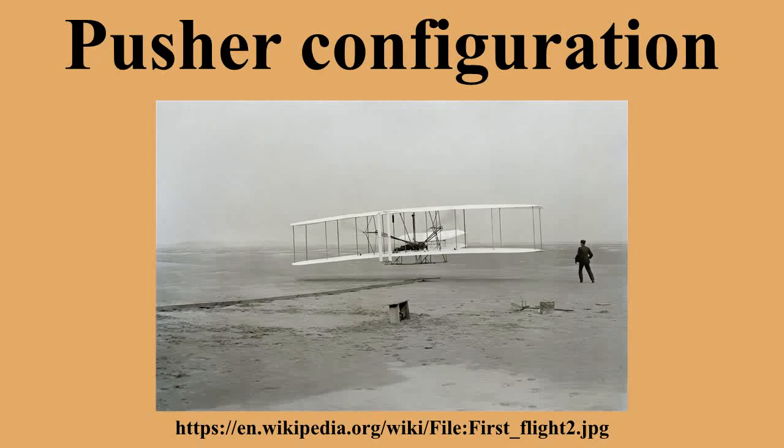Power plant cooling design is more complex than for the tractor configuration, where the propeller forces air through the system. Configurations. Aerostatic airships are the oldest type of pusher aircraft, going back to Frenchman Henri Giffard's pioneering airship of 1852. Aerodyne pusher aircraft have been built in many different configurations. In the vast majority of fixed-wing aircraft, the propellers are still located just behind the trailing edge of the main lifting surface, or below the wing, with the engine being located behind the crew position.